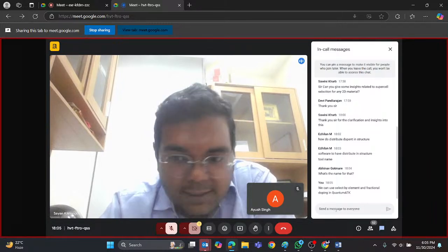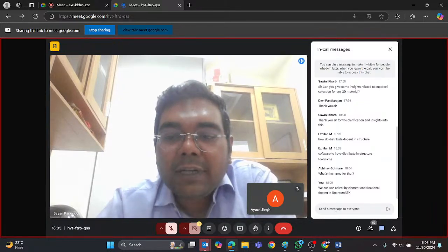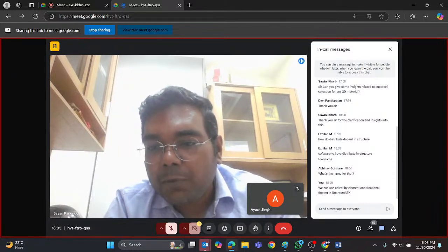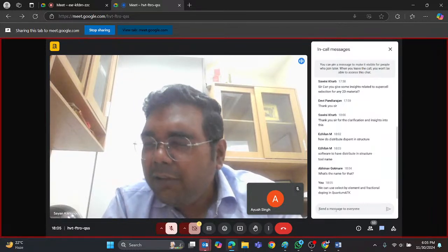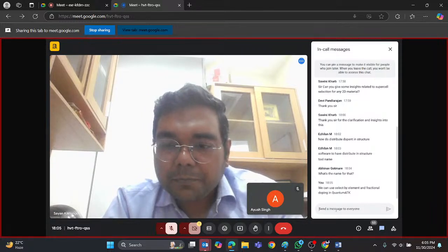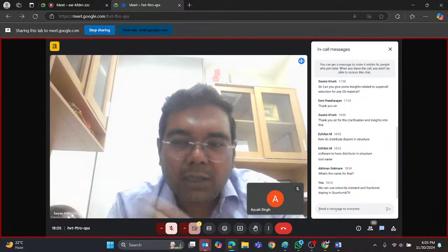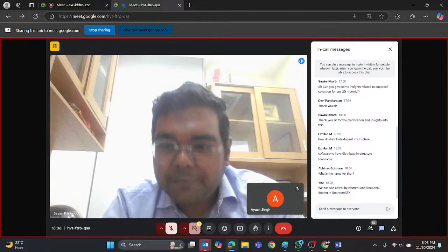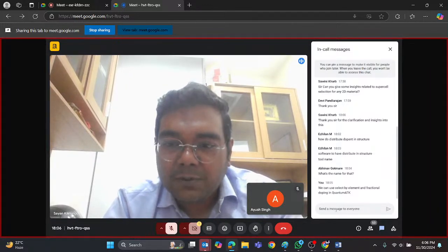If you do a literature survey, you'll be able to see that. For example, in VASP, you have to give the force tolerance, something in the order of 0.01 eV per angstrom, if I can recall correctly. The specific Quantum ESPRESSO part I cannot recall right now because it has been some time since I have actively used Quantum ESPRESSO.